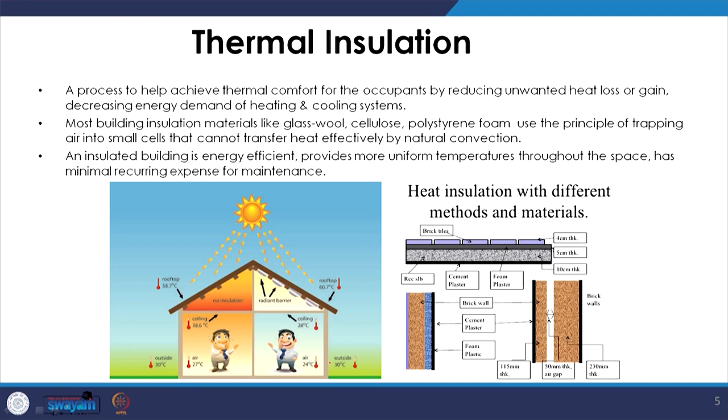While in an extremely cold climate where the outdoor temperatures fall much below the sub-zero temperatures, the insulation may be slightly towards the outside, but both the sides being covered with building materials.